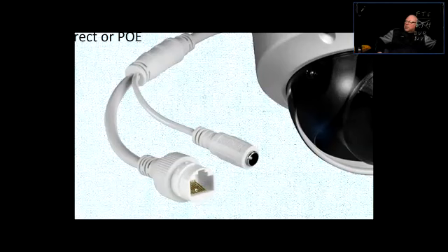However, quite often what you're going to see is that the cameras are being powered from PoE. PoE is power over Ethernet, which means the Ethernet cable is not only responsible for carrying the signal back and forth, but in some pins there would usually be 48 volts DC power, and when this is connected to the receiving end, there's a circuitry that discriminates between the power and the signal. So that's the idea of PoE.